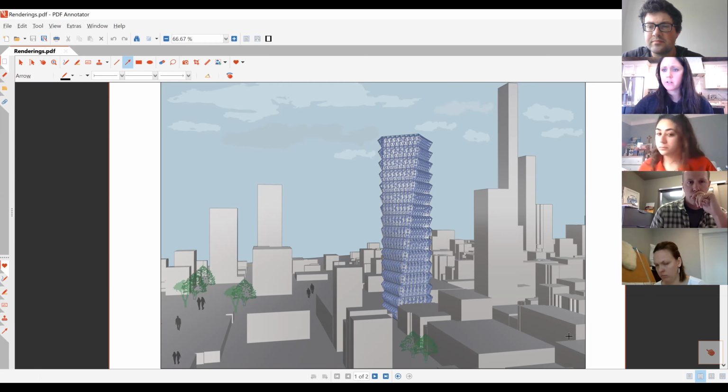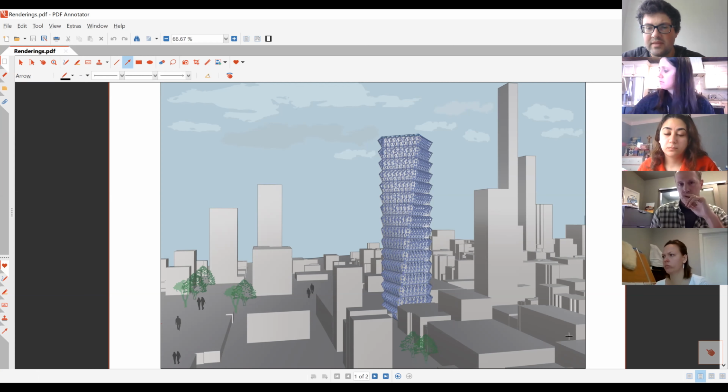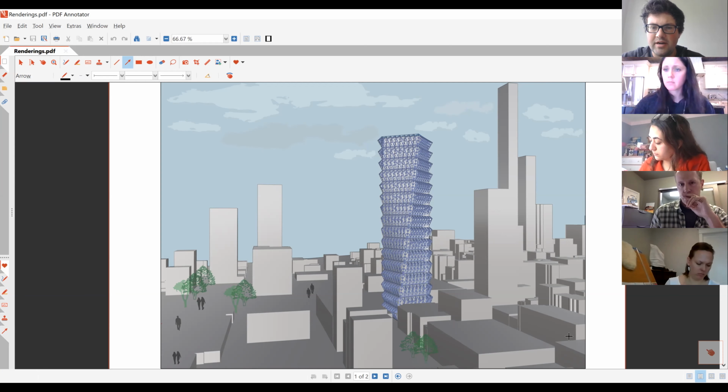How do we get our materiality in Rhino? You'd have to Photoshop that, though. You can Photoshop it. There is a way you can assign materials per layer, and then you can create your own material. It's very similar to SketchUp, where you can adjust some settings, except that it can actually render. So you can adjust the glossiness, the shine, the bump, and then you can have it render out.